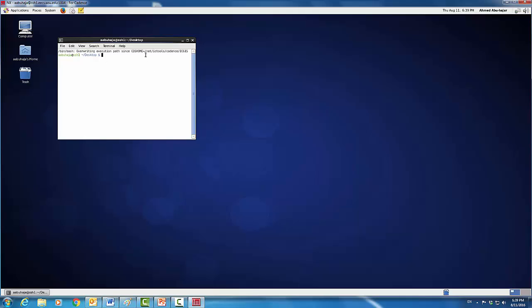And now I'm going to move to the Cadence directory that I have created early on from the previous tutorial. So I'm gonna do cd, which stands for change directory, and then I'm gonna use the tilde, which stands for the home or the root directory of my home directory. And then I'm gonna go to class, then slash, I'm gonna do EE311, that is the course number, and then I'm gonna write cadence.